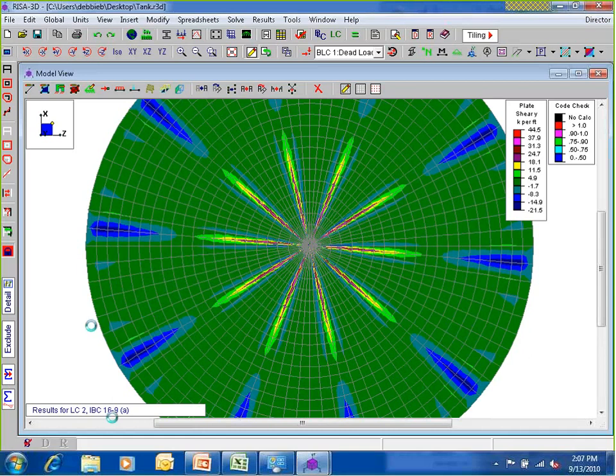You can click on that little icon there, and what you get is a little saw that shows up on your screen. What it's going to be asking you to do is click two points, or what we call a cutting plane. You can click any node on your model. You can see that the first node I clicked gives me a red line. The second node I click creates a cutting plane. That cutting plane allows me to summate along this line. So what we're doing is a summation of forces along that line.